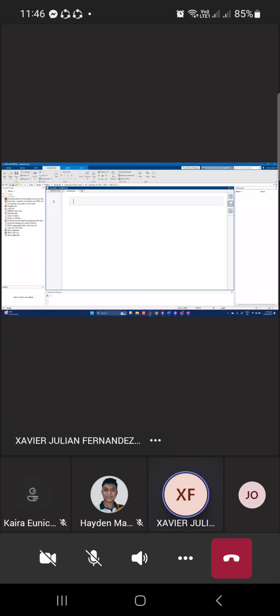First, let us define the transfer functions. First is the controller, which is just 1. We can write it as tf of 1 over 0s plus 1, since 1 over 1 works. Or you can just set C equals 1 directly, as a gain.